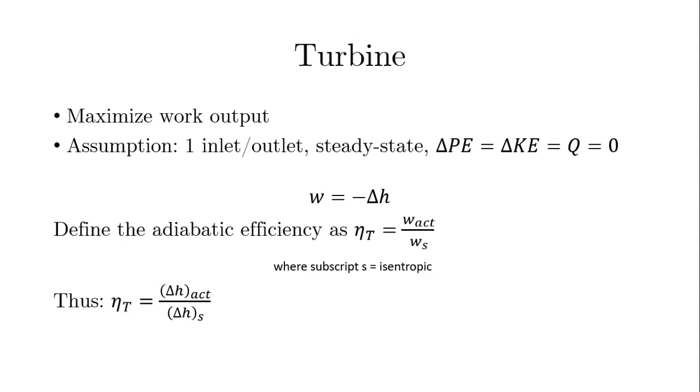What you do is you put maybe a thermometer in it or a barometer in it or whatever you want, and you look at the output of your measurement. And when your measurement is constant with time, that's when steady state occurs, or approximately constant with time, of course. If it's going to change a little bit, you're going to wait for the fluctuations to stabilize. And that's when you can impose the steady state assumption. And that's true for a flow through a turbine, a compressor, a pump, whatever you want.